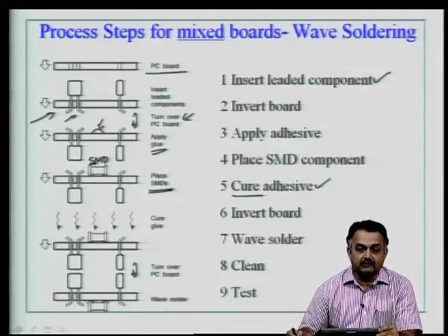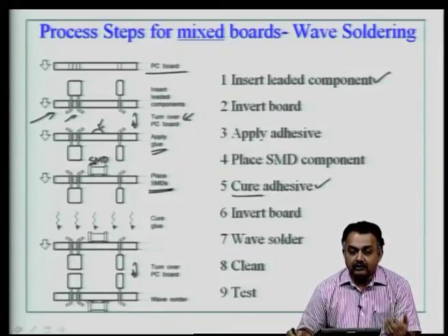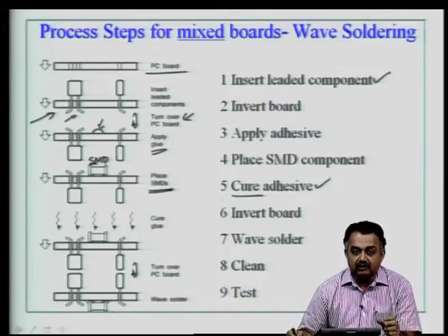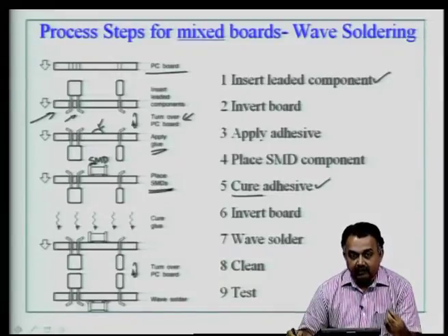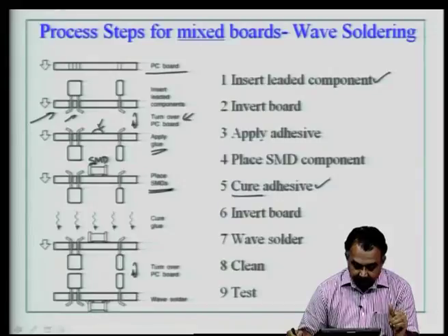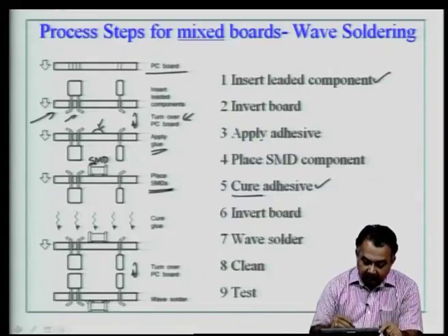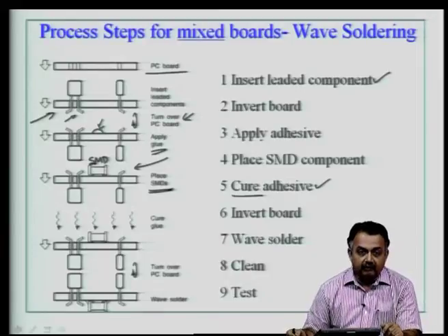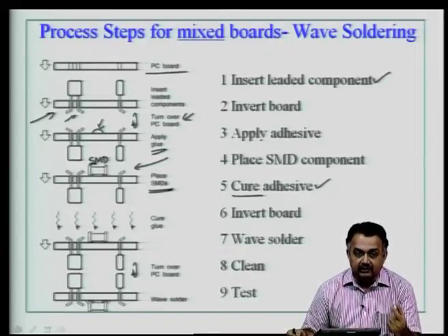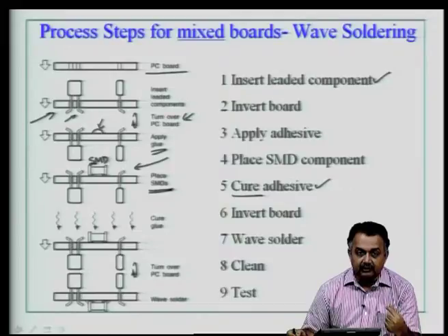Typically, epoxy adhesives are used, and you can use temperatures around 80 to 100 degrees centigrade for about 10 minutes to cure the adhesive and make the SMD firmly placed in its position. Because remember, we are now going to use this side of the board for wave soldering, and simultaneously both the through hole components and the SMD devices are going to be soldered.